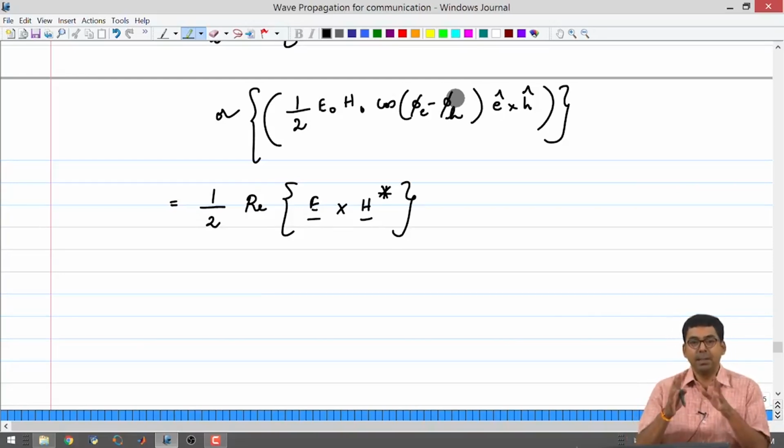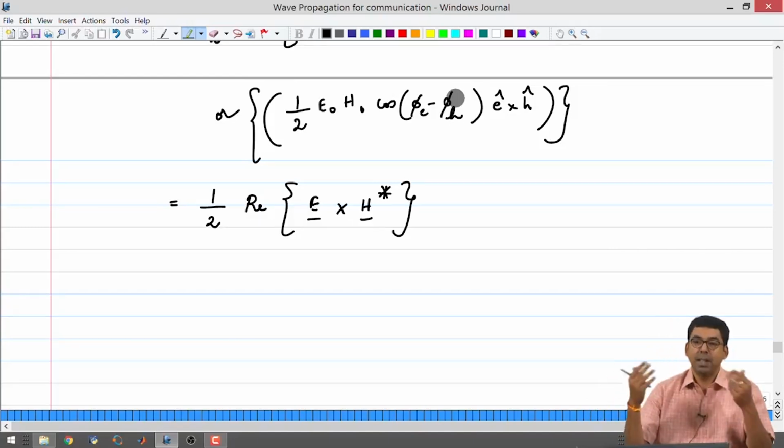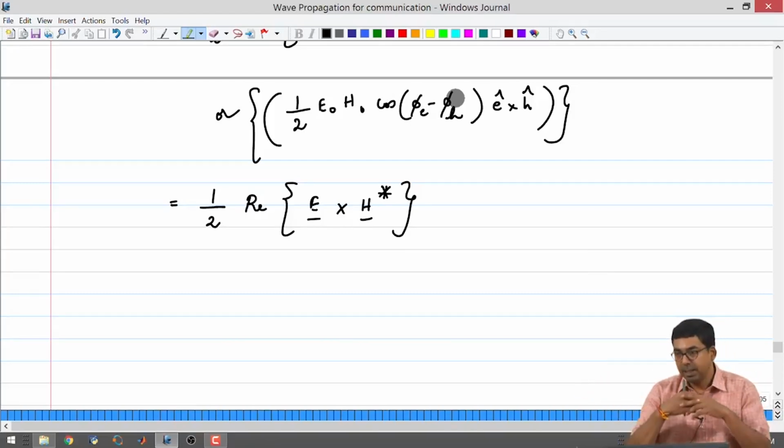In a resistor, the current and the voltage are in phase and the power will simply be V times I. If you want to be very specific, you can say V times I cos phi, where cos phi is your power factor, or phi is the phase difference between your current and voltage. Because phi is equal to 0 degrees, cos phi is 1 and you get VI watts.